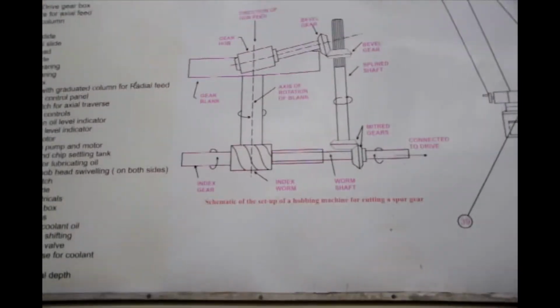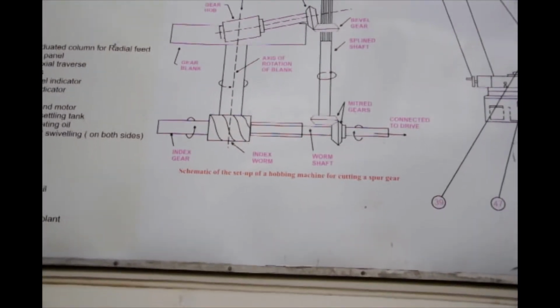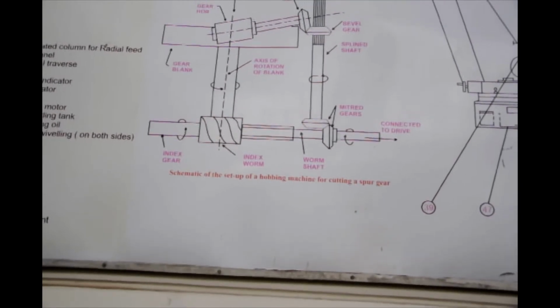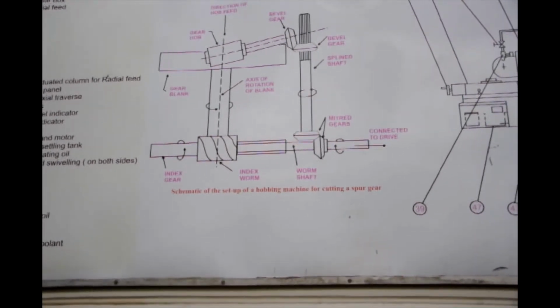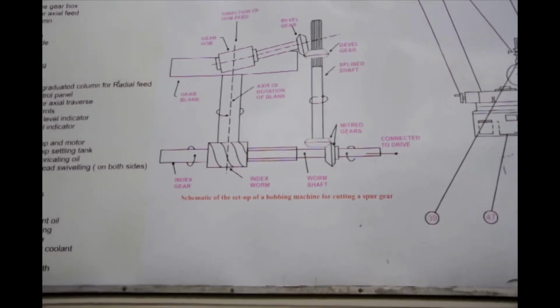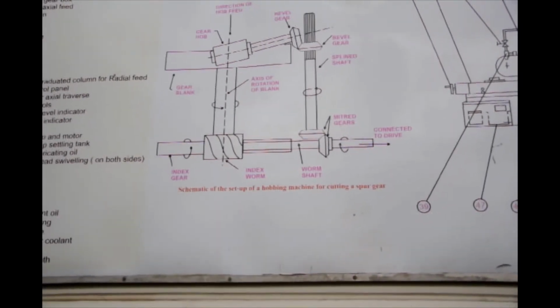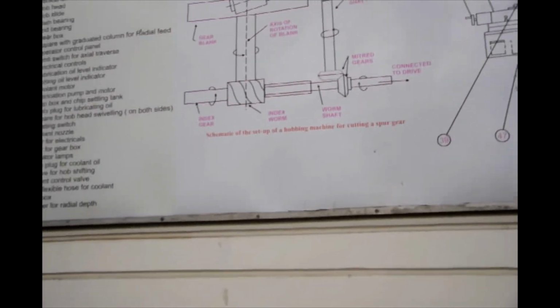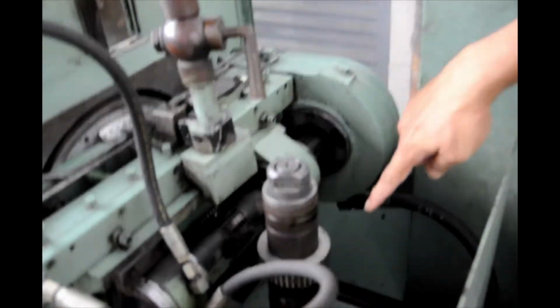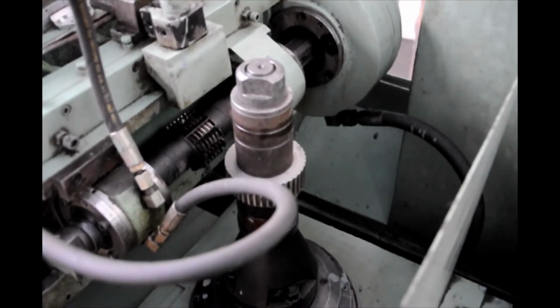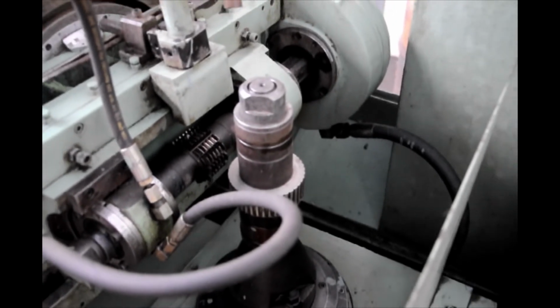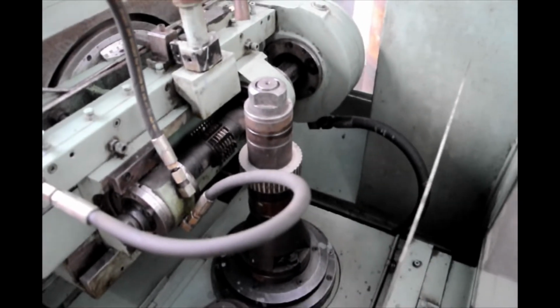So this is also a production machine, and here we can produce things with a limited variety, but unfortunately this gear hobbing machine cannot produce spline shafts. Better models can produce spline shafts where there is no keyway, and the shaft acts as a gear as well as a shaft. Here you can see the cut of the workpiece, and there is the hob. A typical angle can be set for different helix angles, but dedicated hobs are used in those cases.